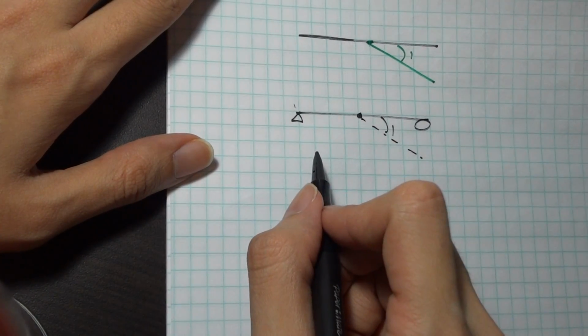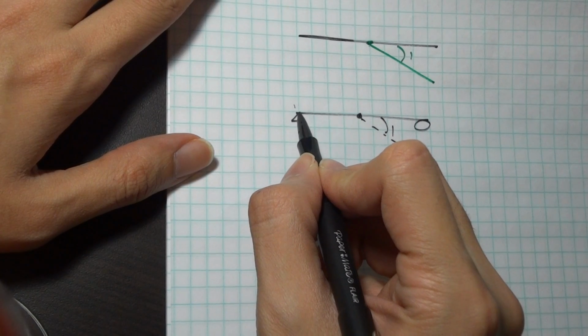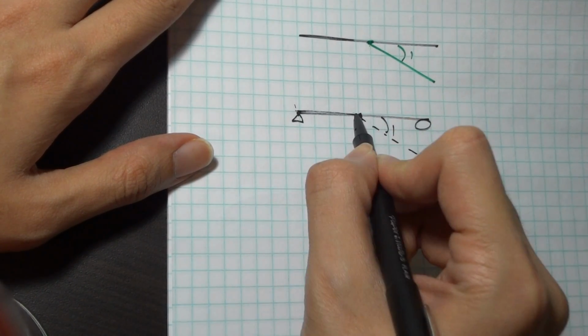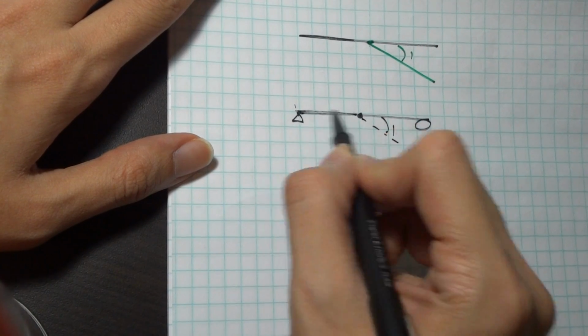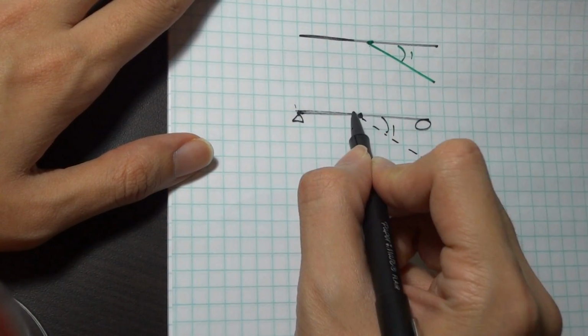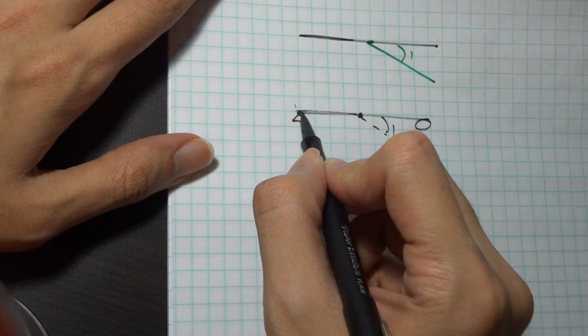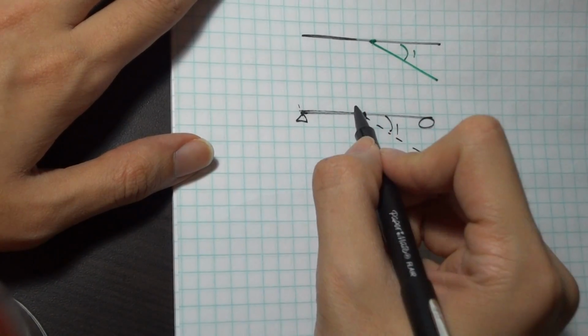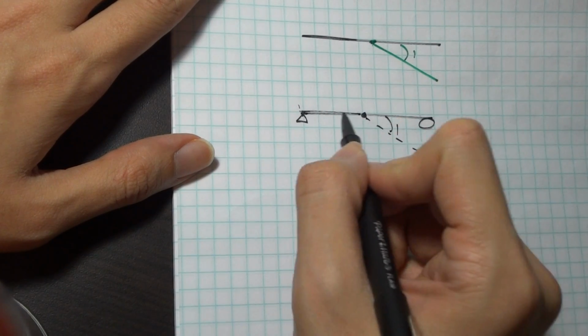I need to maintain my original boundary conditions. This has to have 0 deflection here, right? For Moeller-Breslau, I'm treating this as a physical system. I bent my beam at the point I was interested in, but the arms, the members on either side of that point that I bent it about, are going to be rigid. It's going to be straight.